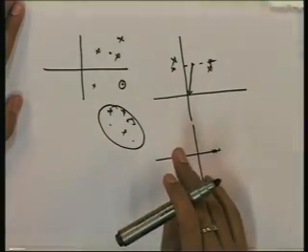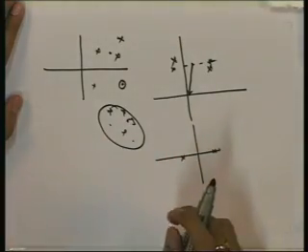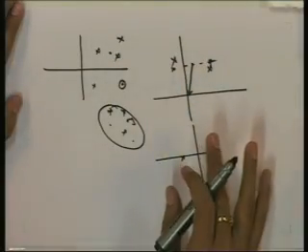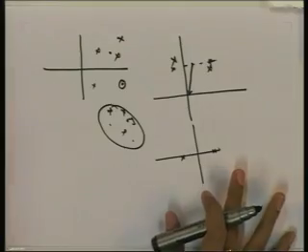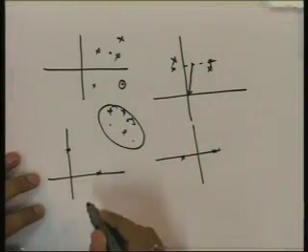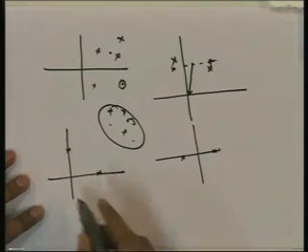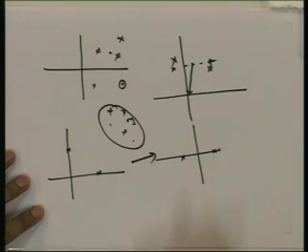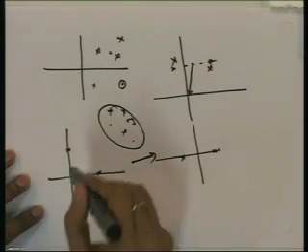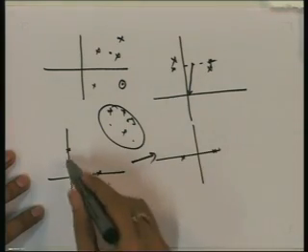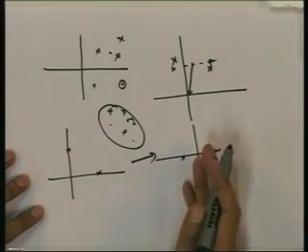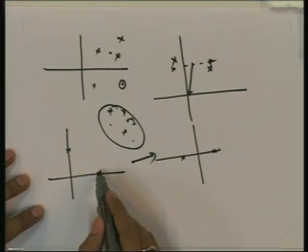So we see that if we are given any 2 points in the constellation we want to transmit, we can also equivalently transmit the translated and rotated version of the signal set. Okay. So similarly, if we use binary FSK, orthogonal FSK, it will be like this. I can say this is also equivalent to translating and rotating to bring it to this type. So performance-wise, reliability or probability of error wise, this signal set will be the same as this, but this will probably use more bandwidth.